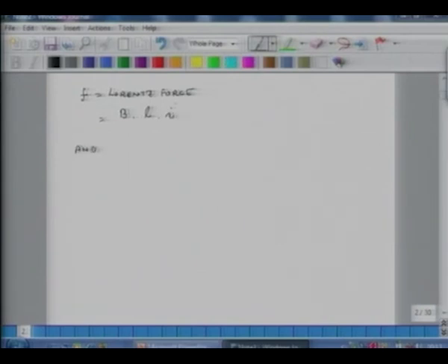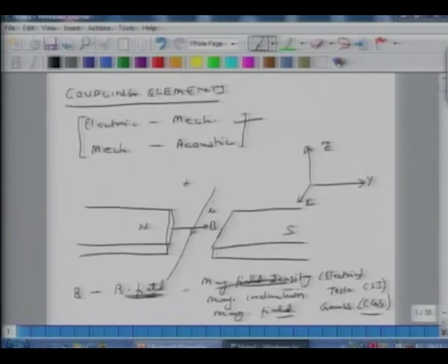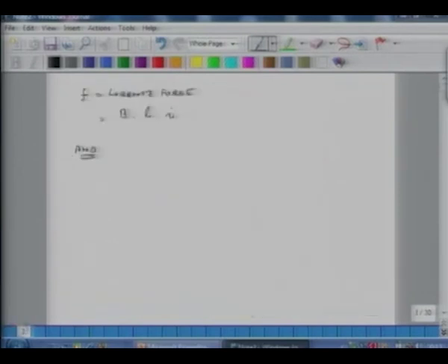And the potential difference across this conductor would be voltage equals B times L times velocity. So this is all standard electromagnetics, and your V is your back EMF and U is velocity. B is magnetic field density, L is the length of the conductor.